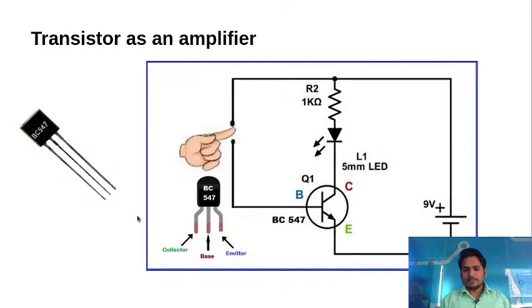Always remember these things, because I have seen many people making mistakes. Many times they make the reverse connection, wrong connection. Due to that, the transistor will start heating, and that is very wrong. It is going to damage all your other components, and it is going to have a bad impact on your circuits, on your microcontroller boards or on other boards.